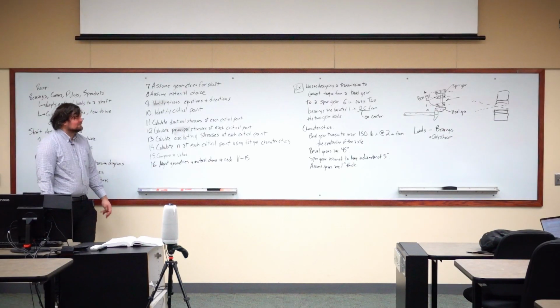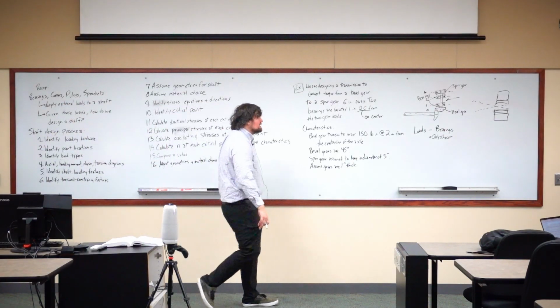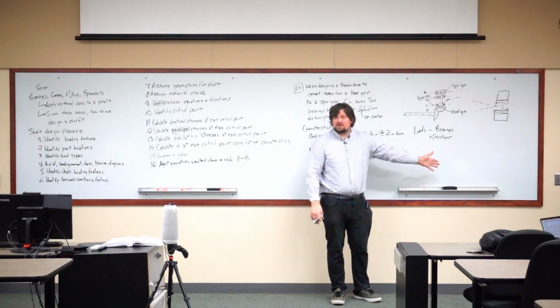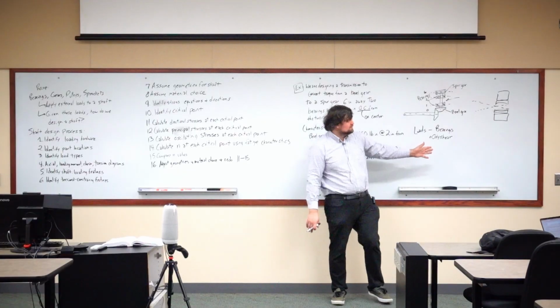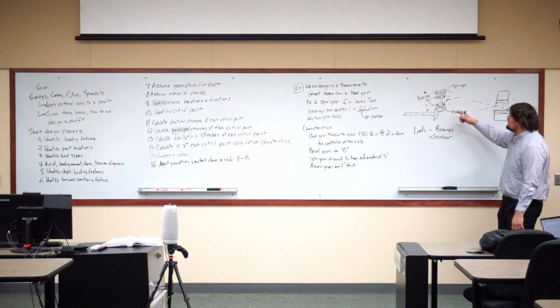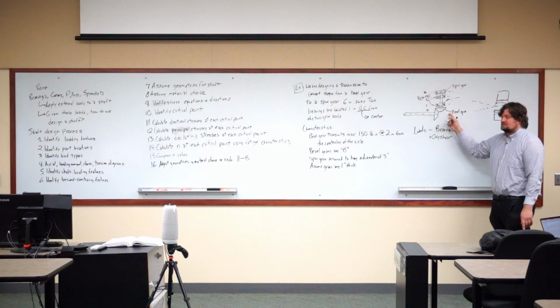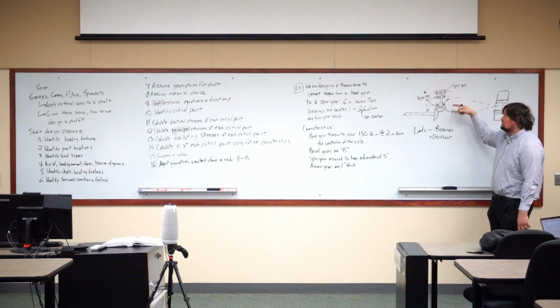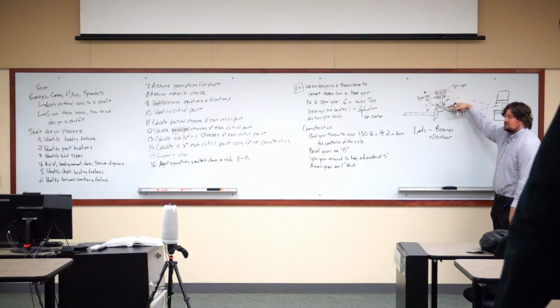That's funny. That's good. Okay, so we're going to assume that the bearings handle only a shear load. Shear load meaning that it's perpendicular to the axis. I can tell you right now, are we going to be dealing with any torsional loads? Yes. On the shaft? Yes. Torsional loads come in here, go out here. Do we have any torsional loads coming out of the bearings?